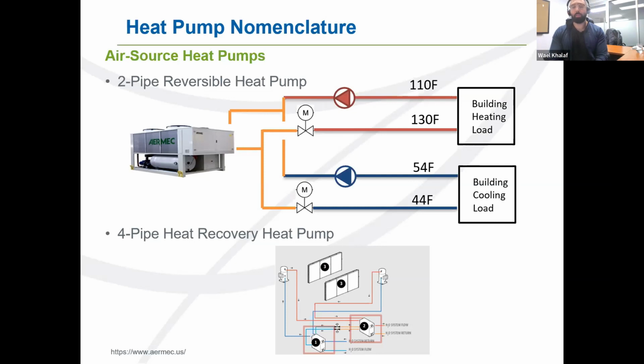One is not dependent on the other. The way we do it is we use the outside condenser coil, or the air coil, to extract heat or reject heat depending on the imbalances in my chilled water and my hot water loop. This type of machine is commonly seen in buildings or applications where I have a year-long demand for both cooling and heating simultaneously.